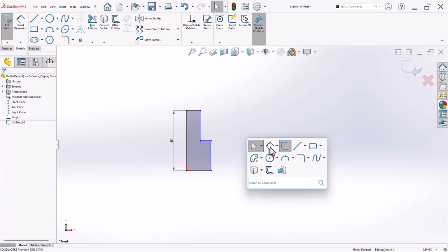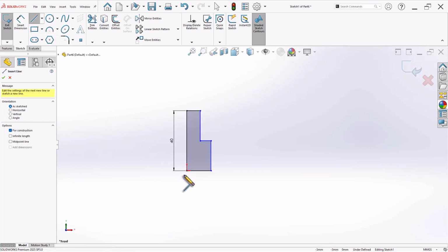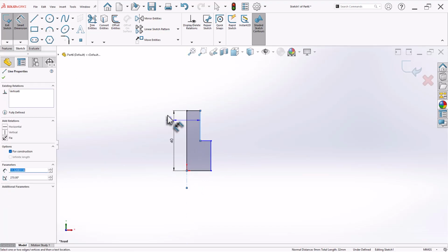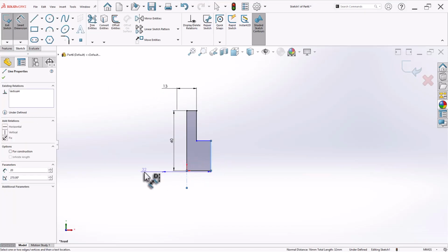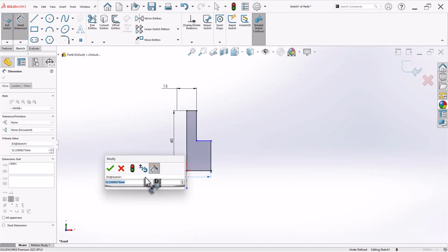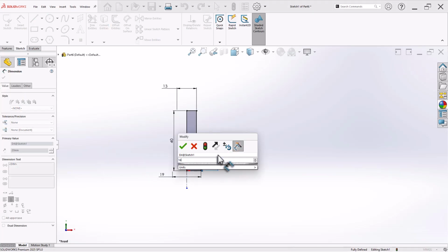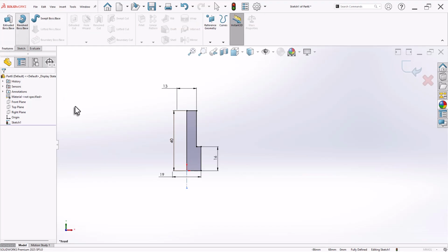Now let's add the dimensions. The top dimensions. Now for that, to create a diameter dimension, we require a center line. So let's select this and this, which is 13. Similarly, here it is given as 19. This height is 16. So let's use the revolve feature.